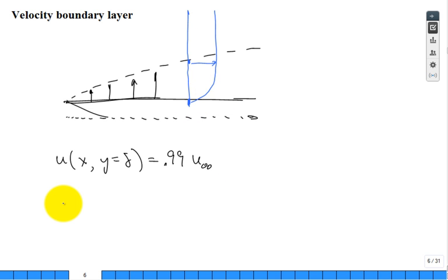And so we have an equation from fluid mechanics, the law of viscosity, that tau is equal to mu du dy. Where did that come from? The law of viscosity. Maybe you have a different name for it in your other fluid mechanics textbook, maybe not. Most of it's just called the law of viscosity. Here it is. So the shear stress at the surface, S, I evaluate that du dy at the surface, S.